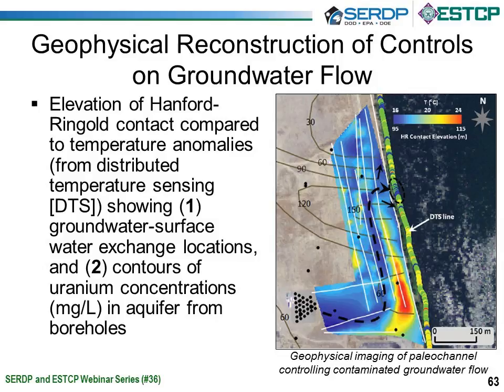So what you see along the river are the results of a fiber optic distributed temperature sensing survey. This data was collected during a low river stage, so presumably lower temperatures likely represent exchange of the groundwater to the surface water. At the outlet of that proposed groundwater surface water exchange pathway, the temperature is lower than other areas on the profile. So this supports evidence of a discharge of groundwater to the river at this location.